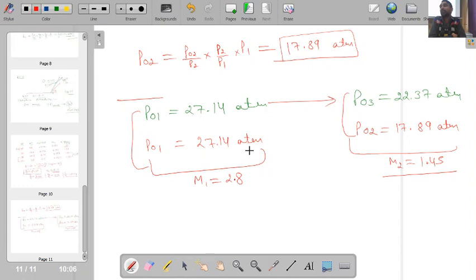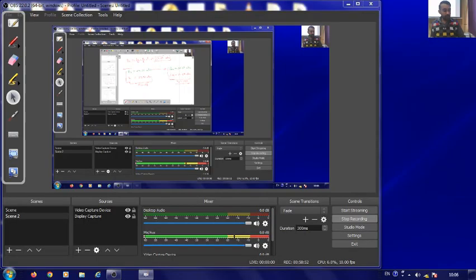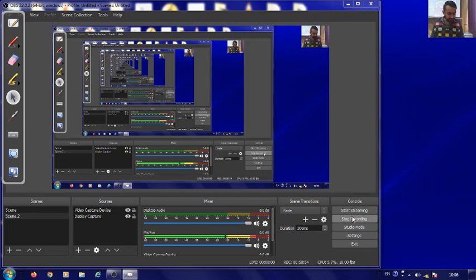Similarly, if you want to design the diffuser section of a wind tunnel, okay, so in the diffuser section of a high pressure wind tunnel also, we try to design it using the shock reflections, because shock reflections will give us better preservation of the pressure. There will be less pressure drop. Okay, so now with this we will stop, and then we will have further discussion in our next lecture.